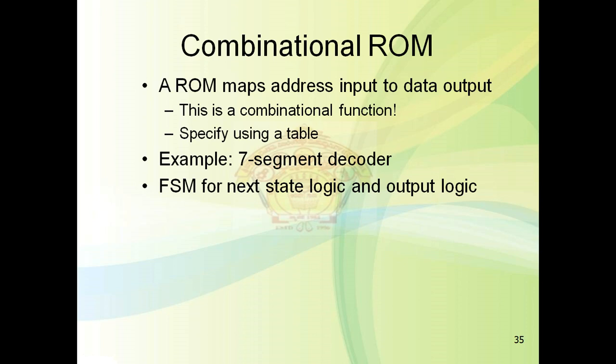And so you know this program that we have written, and as there are 5 inputs, we require 2 raised to 5 memory locations. Now you can see how the combinational logic is designed for it in detail in the book. Okay, this is about the combinational ROM.